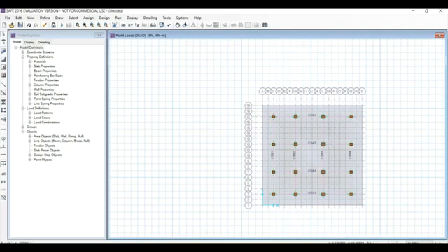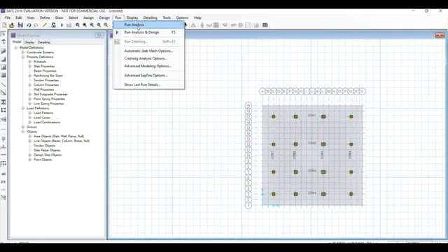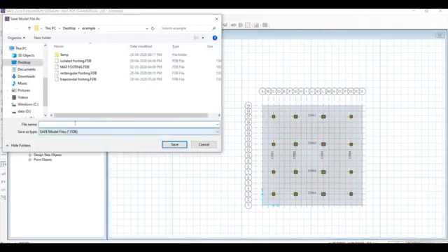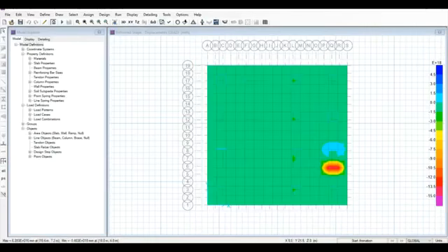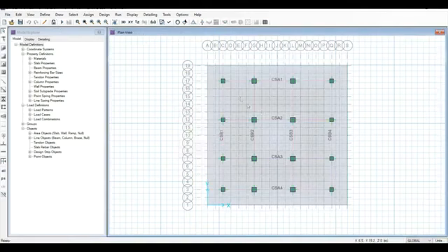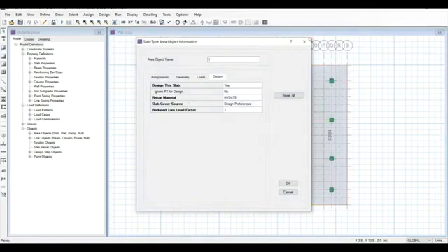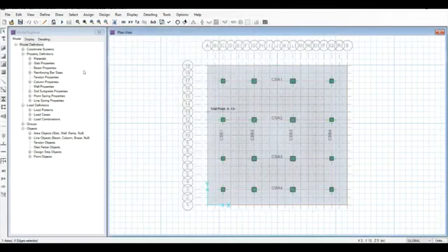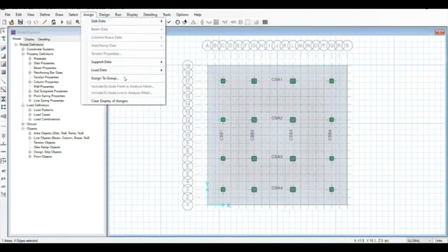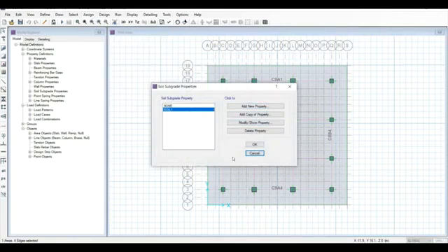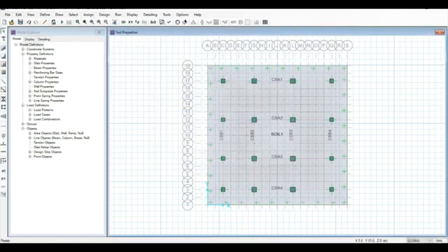Now all the loads have been assigned. Now just run the analysis. Give the name. Okay. As we can see, the design has some fault, since we have not assigned the soil properties and support conditions. So left click on the footing, one area and 4 edges are selected, and go for assign support data, soil properties. As we have already given the soil 1 properties, click OK. Soil properties are also given. Then run analysis.